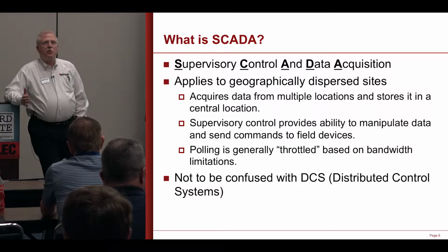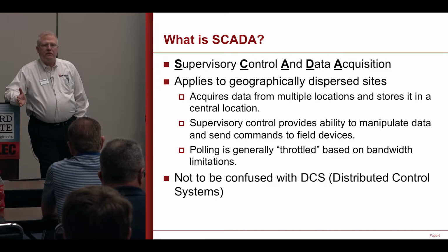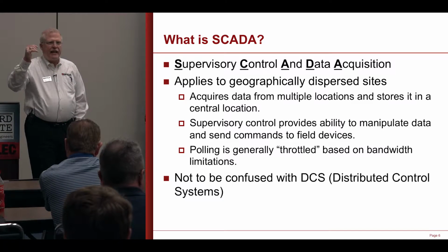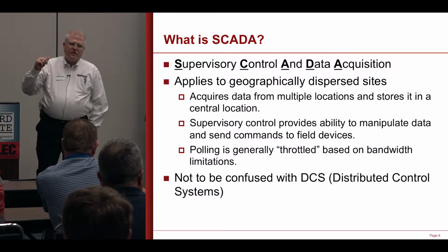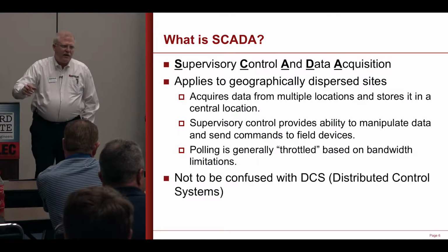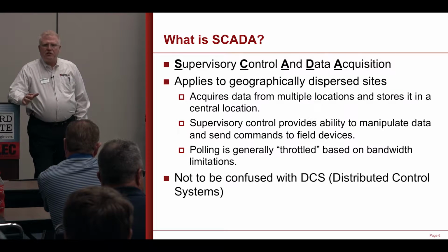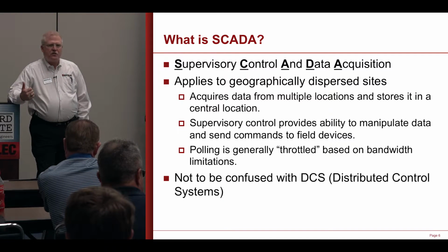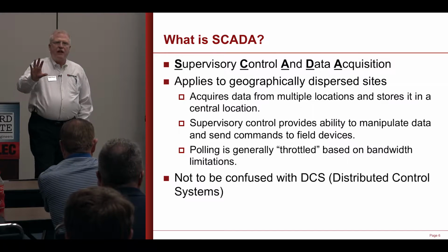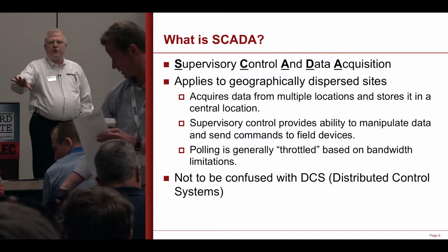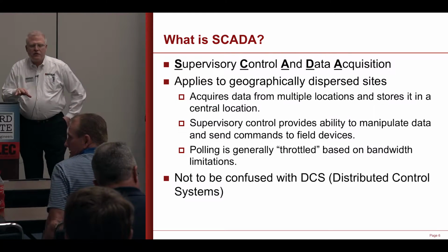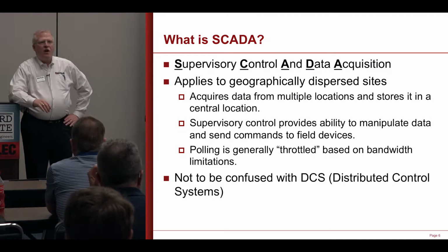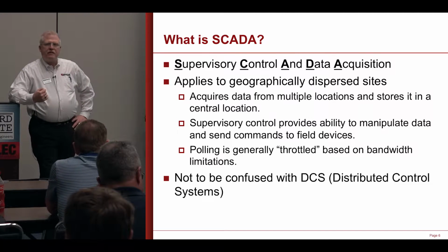What's the most unreliable part of a SCADA system? Communications. The further I get out in the woods, the more I lose reliability, right? So these systems are designed so that if there's no communications to the host, I still have control in the field. So the RTUs, the PLCs, those field automation devices, what I do is I pass a supervisory set point.